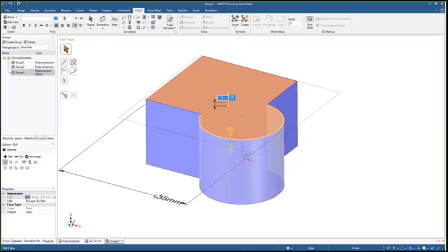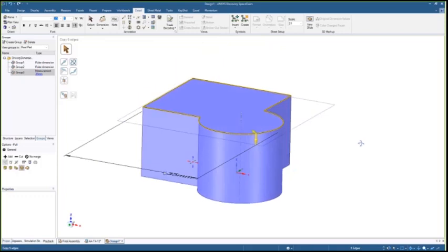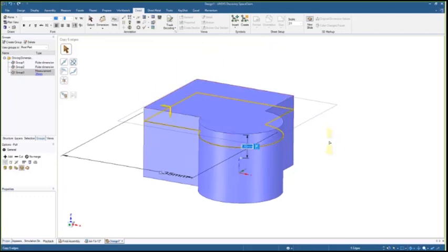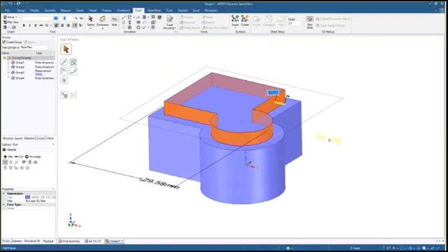And actually, before I do that, one of the great options with pull here is called copy edge. If I switch to copy edge, it either allows me to copy down, and that gives me a new set of faces that I can go ahead and pull. Here I'm scrolling my mouse wheel to select hidden faces, and I could offset that in. I can also, with this option, here I'm double clicking. Double clicking is very popular in SpaceClaim. It allows you to select loops of things.